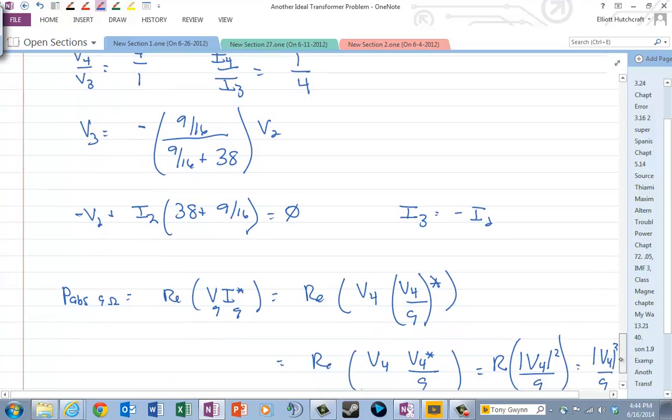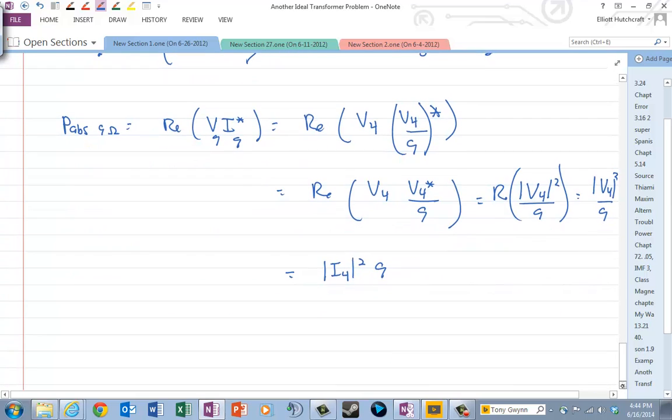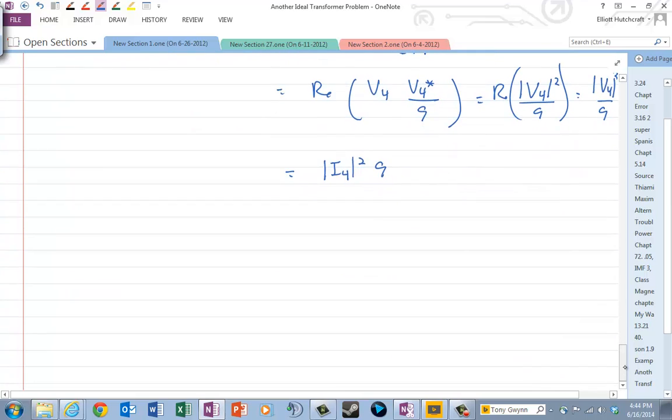So this is a good problem, and it does show you the relationship and how ideal transformers work. One of the most common uses for these ideal transformers is impedance translation, so that you can translate resistances that are smaller to maybe make them bigger on another side of the transformer, and that can hopefully maybe match the resistance for a source so that you can get maximum power transfer.